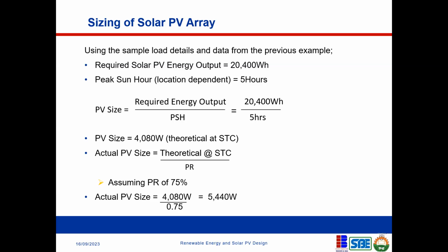If you're expecting your PV panel to produce 5,000 watt hour in 1 month, then after that 1 month, what you actually see that your PV produced was 3,000 watt hour. In actual production, it is 3,000 watt hour. So you divide 3,000 watt hour by 5,000. Let me just run that calculation. 3,000 divided by 5,000. So you find out that for that very installation, your performance ratio is 60%.